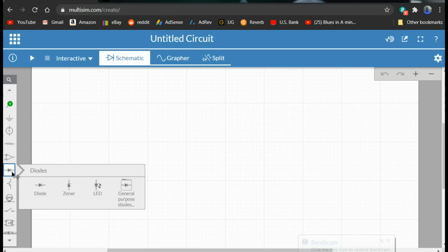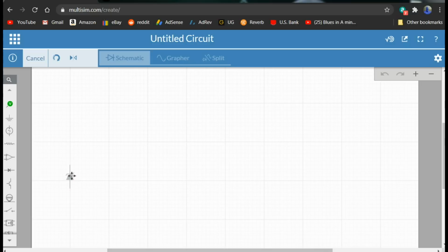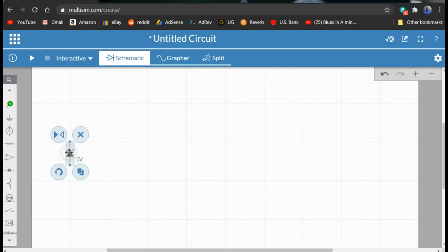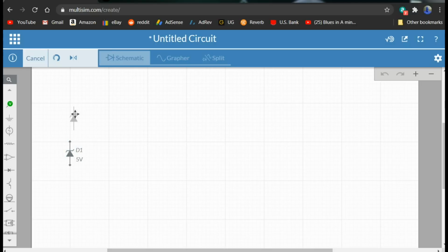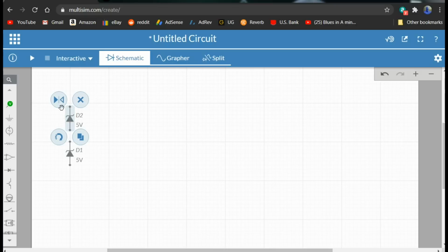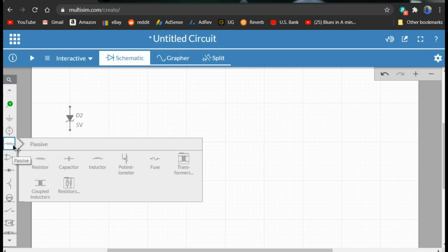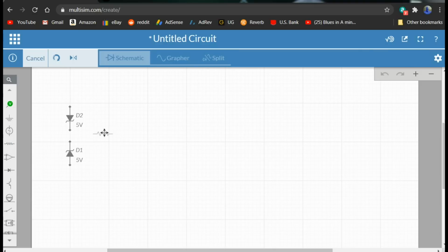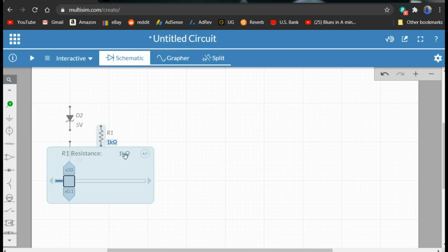Okay, this is Multisim, that we covered in a previous video. So I'm going to draw up the circuit, but I'm going to add a couple more things to it. I'm going to add some face-to-face Zener diodes, and what they're going to do is help us prevent saturation. You see, if the positive feedback gets too much, it can saturate. So the two Zener diodes are placed face-to-face, and they're connected across the upper resistor, which I haven't drawn in yet, but it's going to be about 22K.